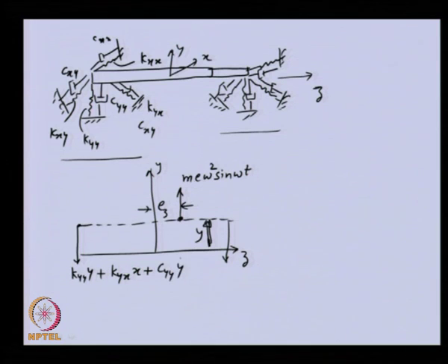Apart from that, we have the damping term also, and we have the cross coupled term due to the damping. So, these are the forces acting at the left hand end. The same force, because I am considering the same bearing in this particular analysis, will act at the other end also, due to the damping and stiffness.